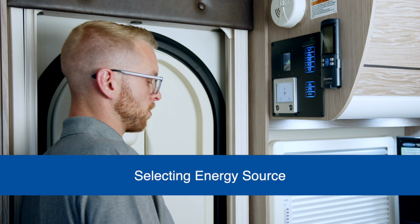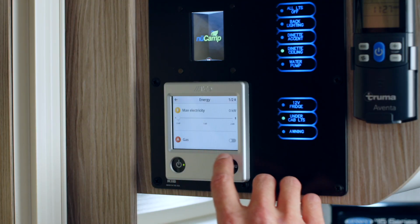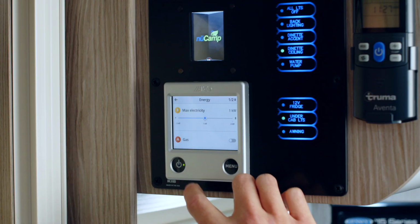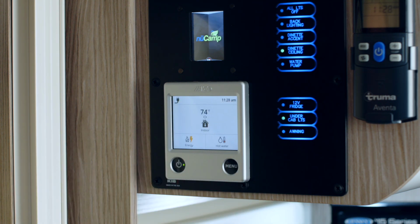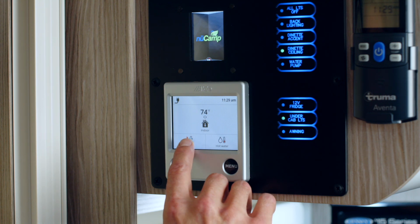The status screen of your Alde control panel shows which energy source is in use at the lower right corner of the screen. Selecting this screen will allow us to change between electricity, gas, both, or prioritize which fuel source we would like to be utilized. We can switch between 1 kilowatt of electric power or 2 kilowatts of electric power. If the lightning bolt is yellow on the status screen, this means electrical is chosen. At the bottom corner of the screen, if the flame is red, this means gas is active.